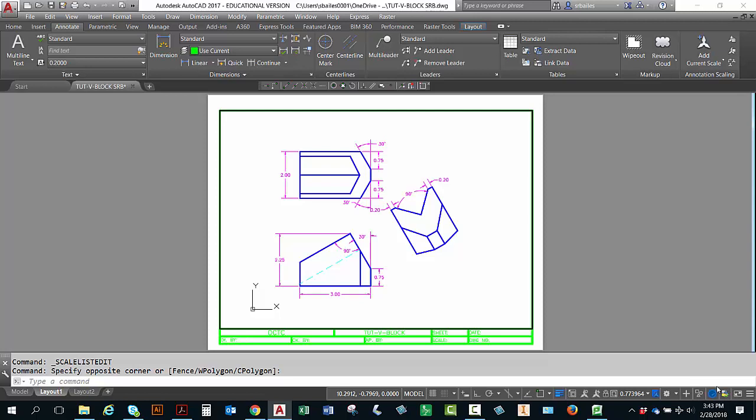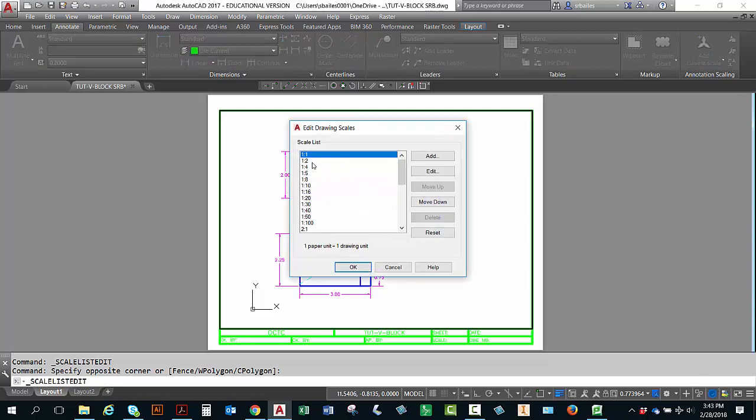So we'll pick custom, and to turn on these extra scales, which are metric, but they are a little easier to understand. Oddly enough, AutoCAD uses architectural scales for their mechanical drawing setup, and the only thing I can surmise is that they are a bit easier to understand, but for me these are a little easier, and they are kind of universal.